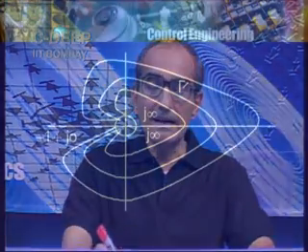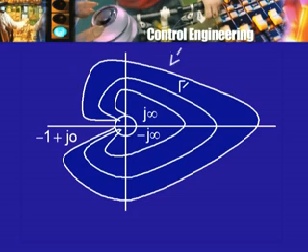from experiment I can determine this upper part, what looks like the upper part here. I take the mirror image in the real axis, so I get this figure, and because the image of the semicircle is virtually a curve which is very close to the origin, I can show it like this actually by joining these two and going to the origin. Although in practice, if I write here j infinity, I do not really mean that I apply a signal of infinite frequency and I make any measurement.